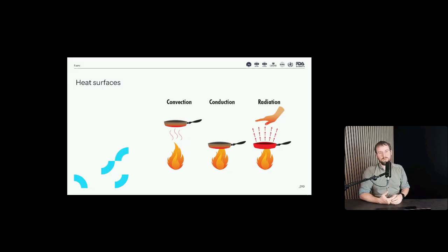And we do see, unfortunately, a lot of cases where you find non-conforming temperatures because you have product placements too close in front of radiators. Often the air is understood to move around and heat the general space, but radiation heating is really one of the items that can cause nonconformities.